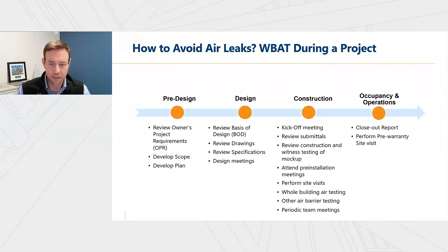Moving next into the construction phase, review of contractor submittals is important. Is there coordination between the trades, including at interfaces between enclosure systems? Are there air barrier shop drawings? Next, the mock-up review is important.